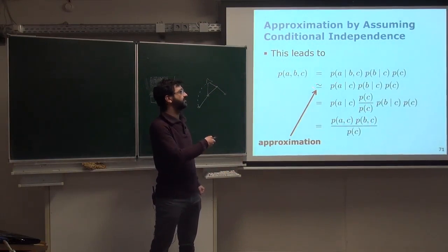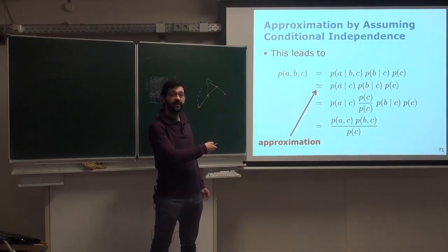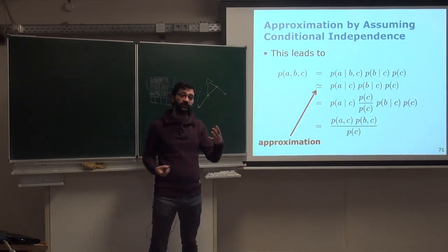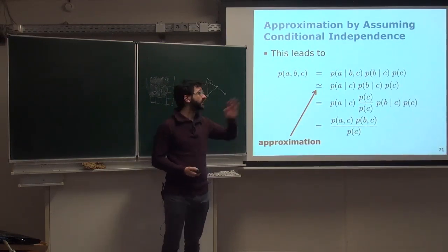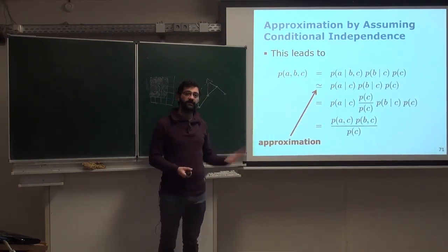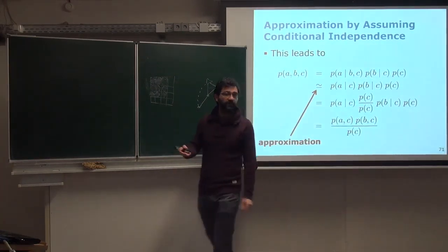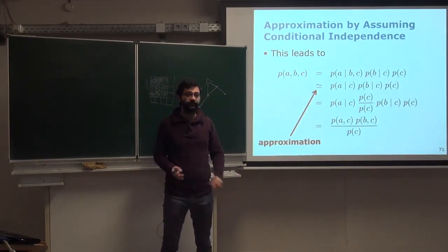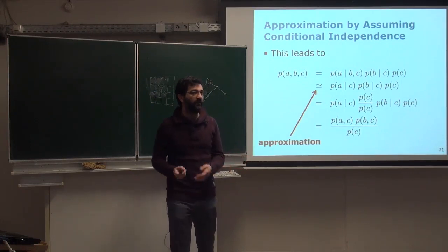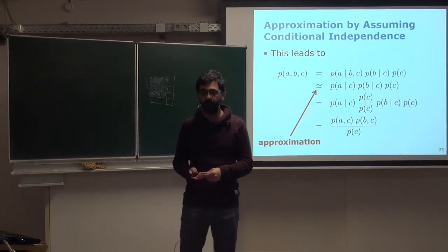This, again, is an approximation because there's no equivalence between these two. They are only equivalent given the conditional independence. And in this case, we are enforcing conditional independence, so it's not in the variables themselves at the beginning. There might be cases where these are really conditionally independent, and then there is an equivalence between the two. Okay? But for sparsification in SEIF, we are enforcing it. So we are losing some information. We are losing accuracy. We are approximating our target distribution. Okay?